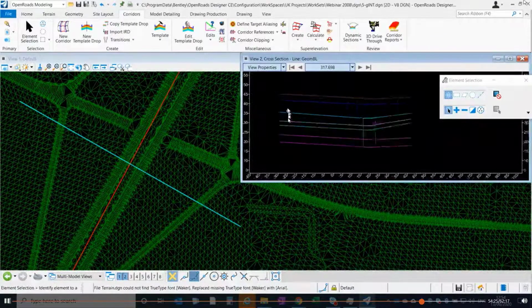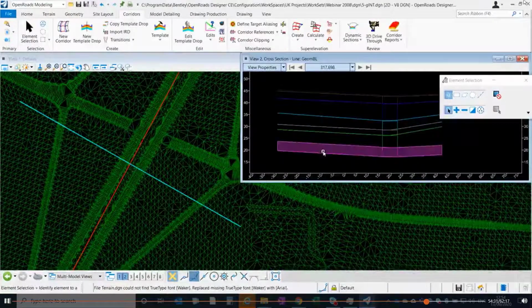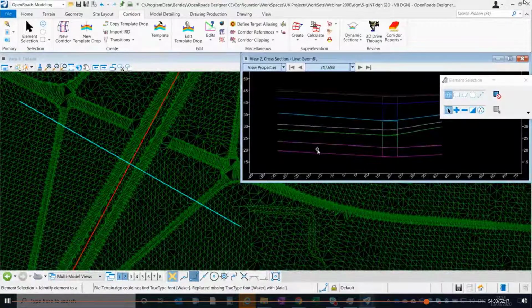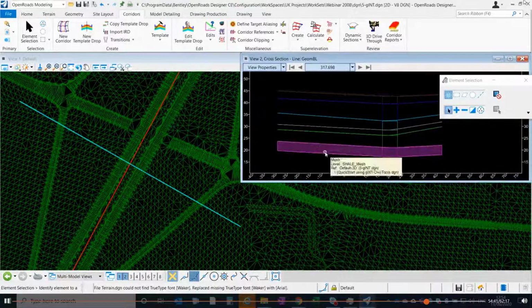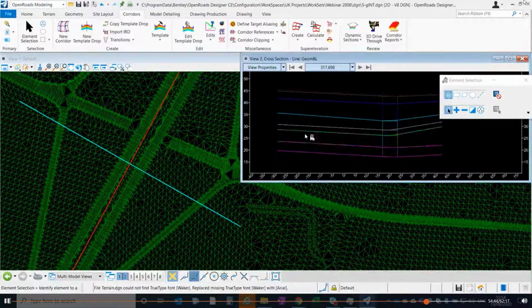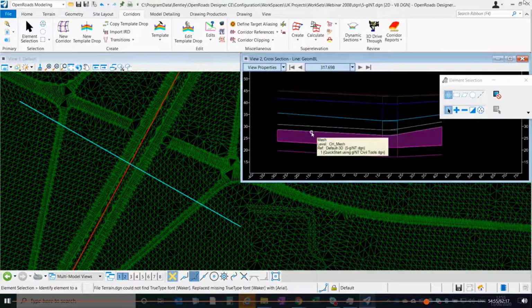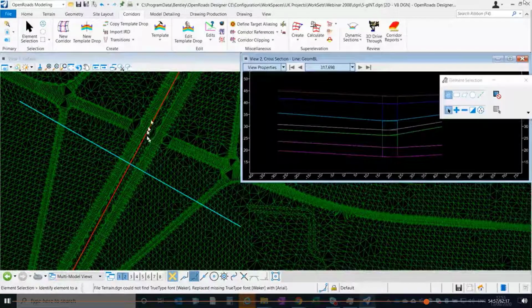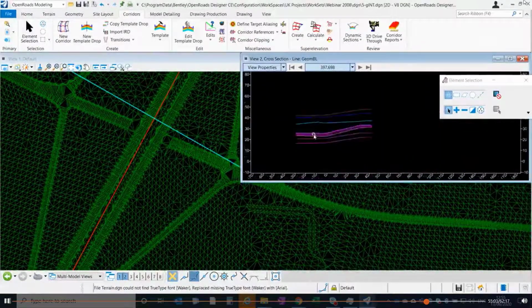And also one thing that is really useful that you could do is to create within your templates, for your corridor, an end condition specific for each layer. So let's say you have a specific slope for these first layers, you will be able to target these layers and then use a different slope for all the different layers that you cross in your project. Okay, and you can see, you can go along, and they're all here.